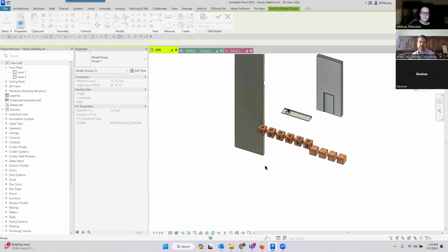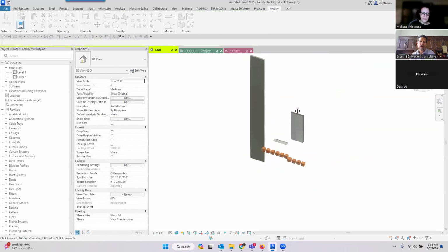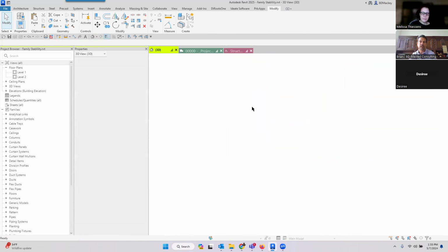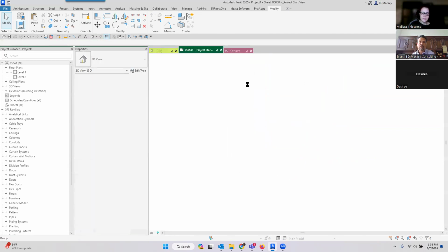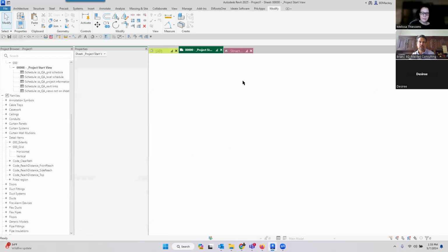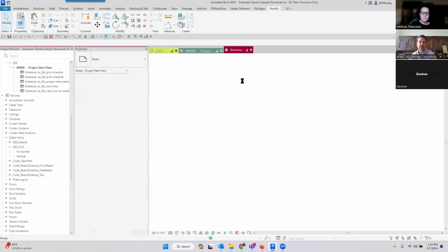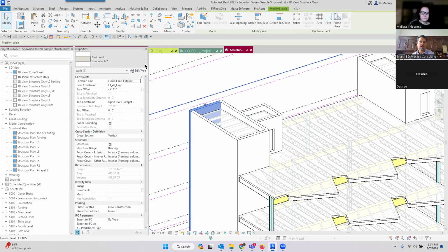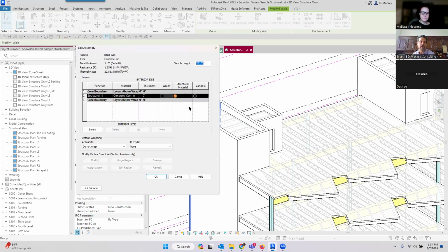What about transfer project standards? Yeah, but usually it's one or two materials, not the whole thing. But let me just check this. Let me come in here. That's not the right project. This one's where I needed to go. Take that same wall we had. Let me edit the type of this and make it something ridiculously wider to see if it'll update. 4 feet, cool.